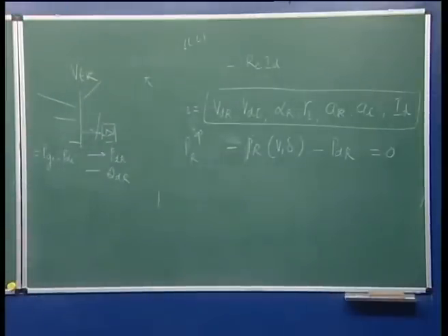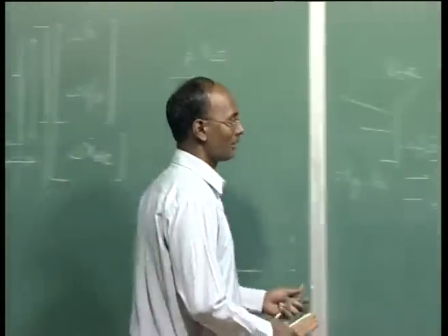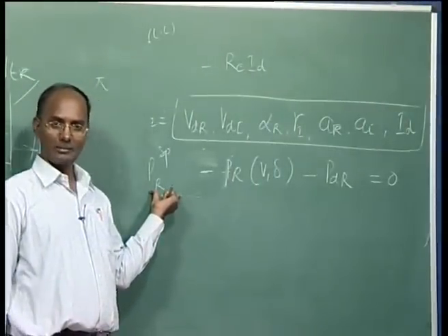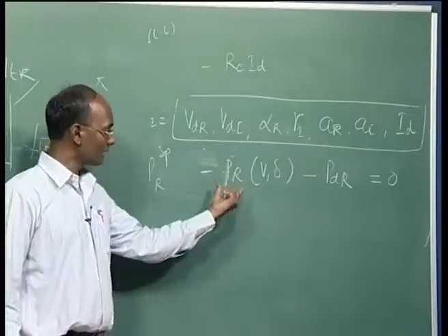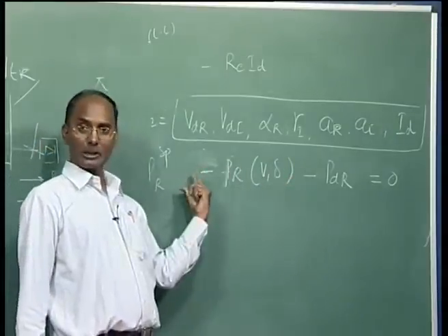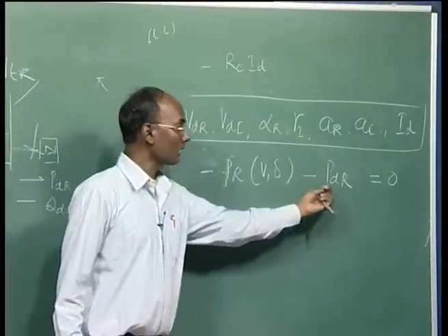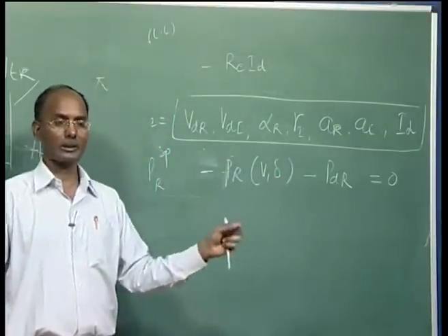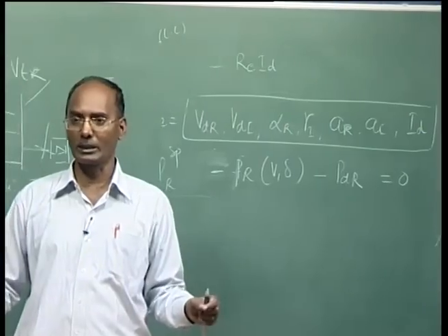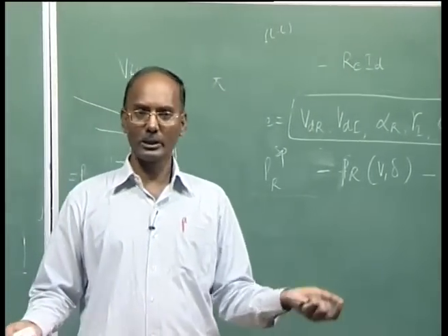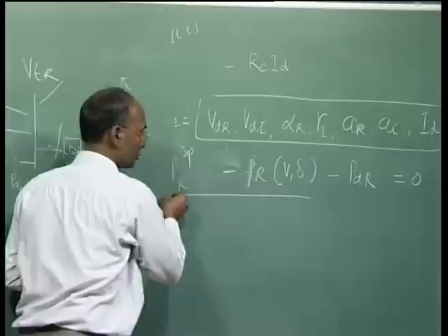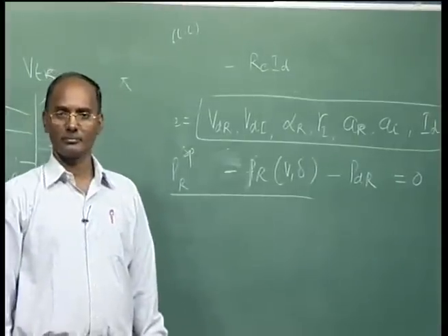Now, what I did? This is your PGI minus PDI specified. This was that side, I keep this side with the minus sign. It was already minus here, we were subtracting. So, we are writing an equation that is Fx is equal to 0, which is a nonlinear equation we are to solve. In the AC Newton Raphson without DC, we solve this equation equal to 0, remember.